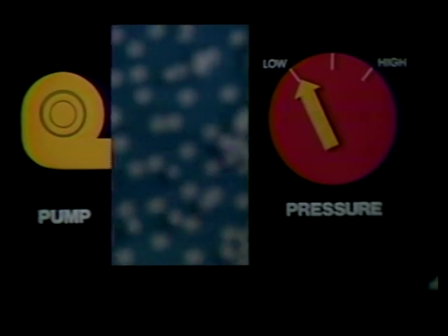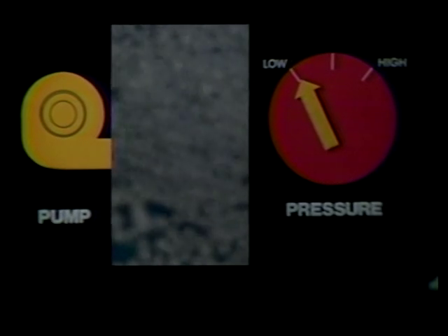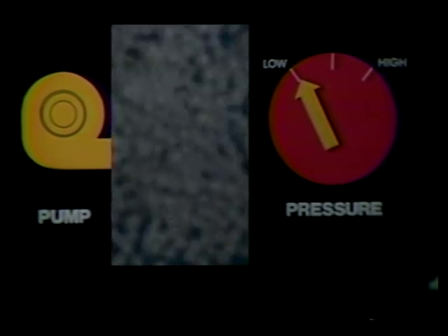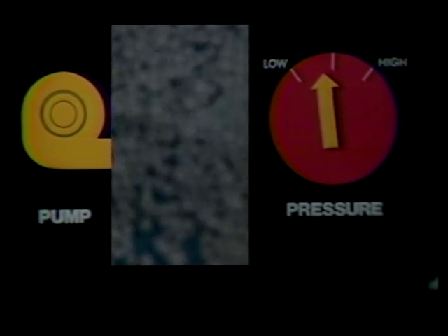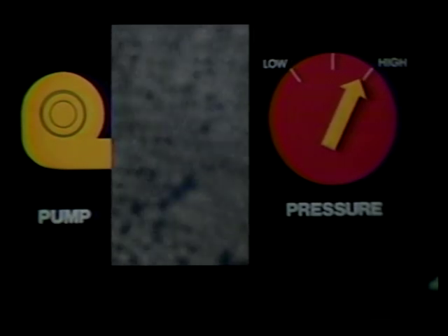Another property of air which is important to turbine operation is compressibility. If we attach a compressor to our container, we can add more air molecules to those already there. Should we continue to pump air into the container, we would see the pressure rise. It's easy to see why. With more molecules, the numbers striking the wall at any given time increases. Since each molecule exerts force on the wall when it collides, it follows that pressure will increase when more molecules are pumped into the container. So energy has been converted into pressure through compression.